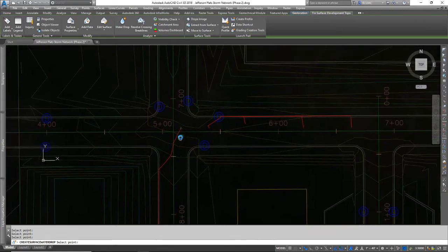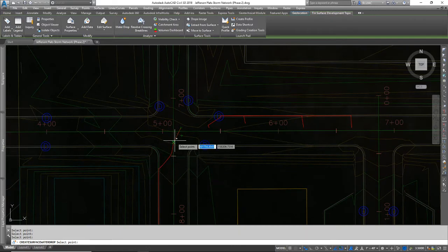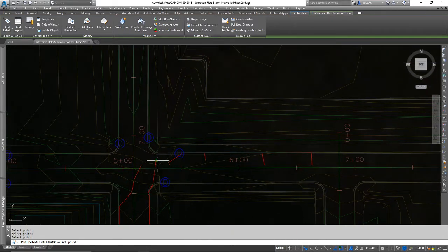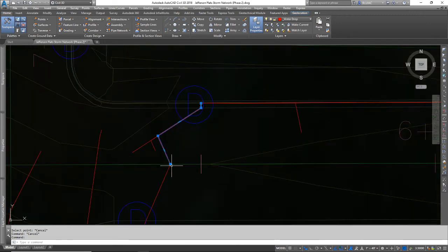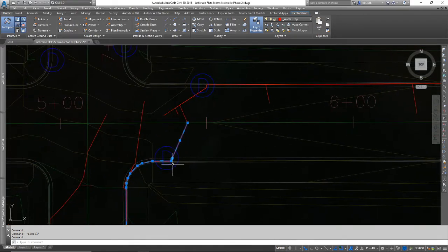And you can see this water drop wants to travel somewhere else, as does that one. So I have to define the boundary of each catchment area. If I hit the center line there, it flows into this catch basin, and this one's going to flow this way.